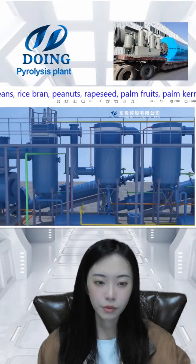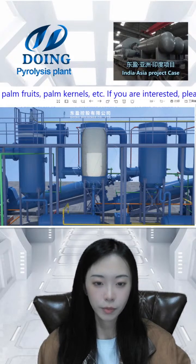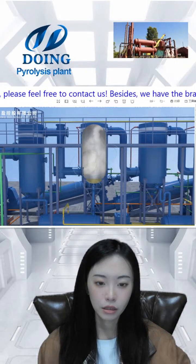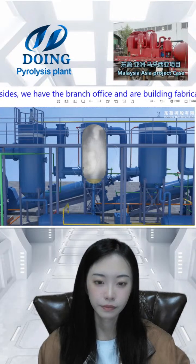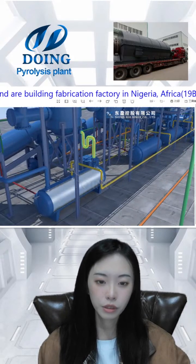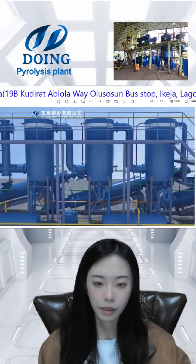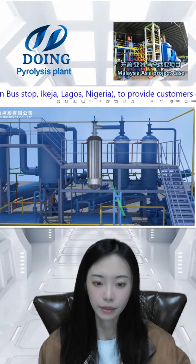And next, we come to the buffer condensation tank. We have 3 tanks to further precipitate the impurities and have a buffer effect. The outside is a water cover, which can condense. It has a good condensing effect. And this is the U-tube design, which is used to balance the pressure and prevent the oil gas from entering the oil tank after the pumping, and the oil will be stored in our 2-ton storage tank.